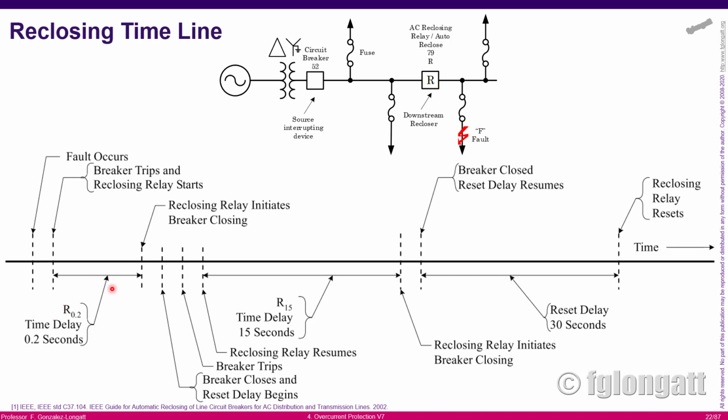Initially, the auto-reclosing delay setting is 0.2 seconds in this case, and then since the closure of the breaker, this is basically using an auxiliary contact that is coming from the breaker and indicates if the breaker is open or closed.